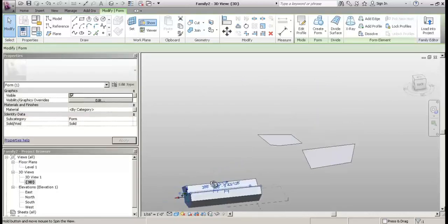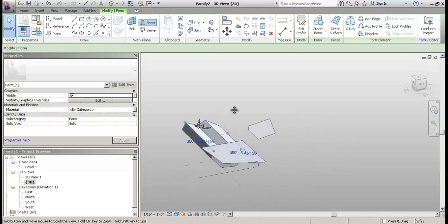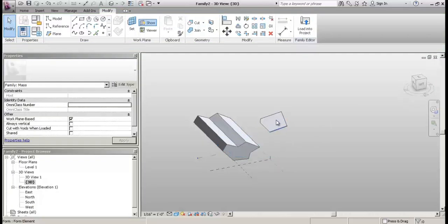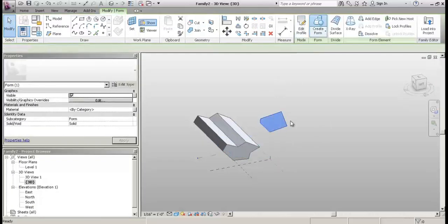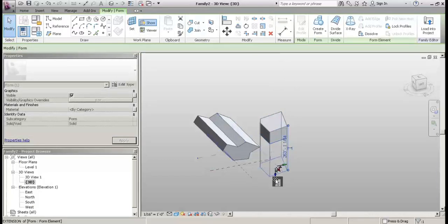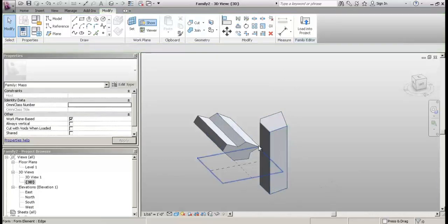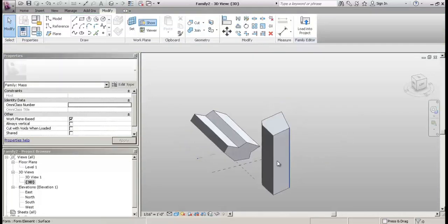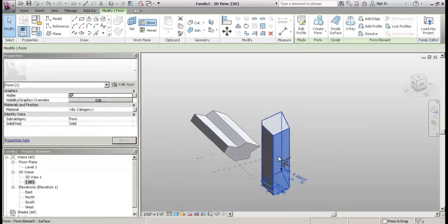And when you have this particular capability, I think you can actually do some better things with it. So if I needed to have this particular top on this building, and all I had was point data to come off of, and I couldn't get the extrusion to come out at the top of it, I would just come in and create form and be able to drag that down. And I would put a void piece, and then I would have my tower that has a slightly curved angle at the top. Okay.